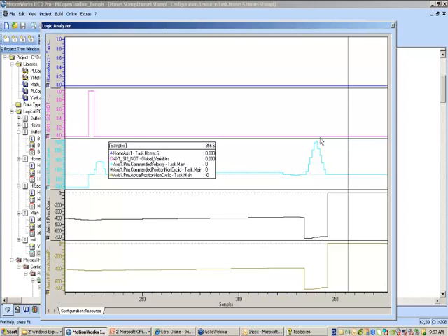Now you see this little dip here in the position. That is because when you search for the C channel, the end of it does actually set a position automatically. So it set a position to 0, and because it's a rotary axis, it rolled to between 0 and 360. So it actually did roll a little bit. But since this offset move is a relative move, it doesn't matter. And what matters is when it gets to the end, it defines the position that we want, which is 0.